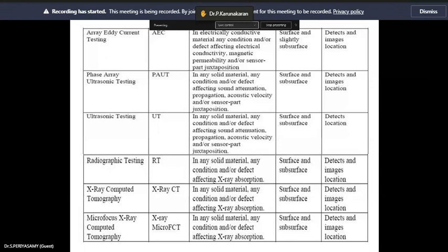In the previous case, even the deposition energy rate, everything is variable. If you are depositing line by line, or unidirectional or bidirectional, the specific energy is varying. What happens is one time, one edge may have less deposition or a high one. Then melting will not be there. Suppose a particle is not melted completely, at that time the particle will go out from the pool.